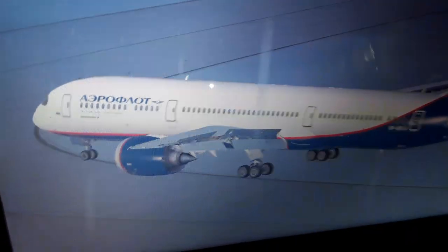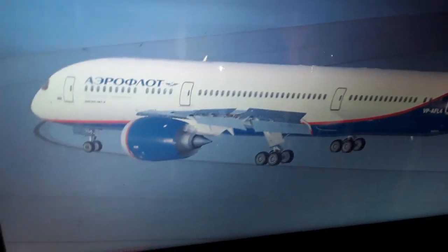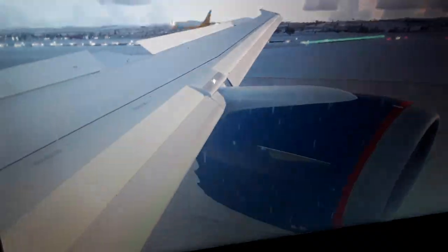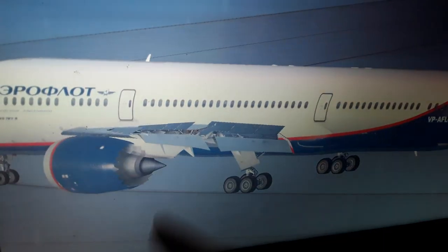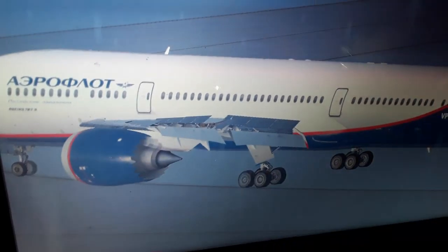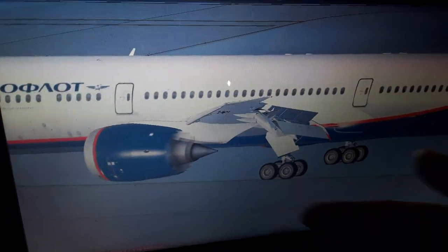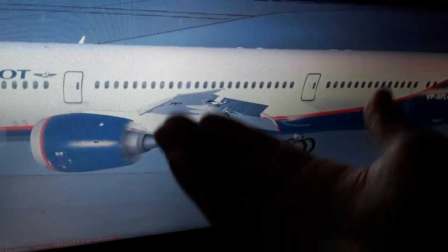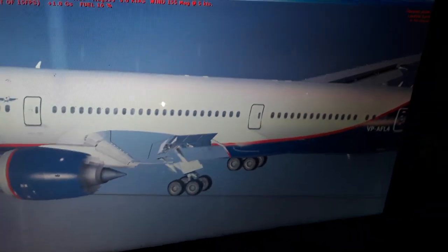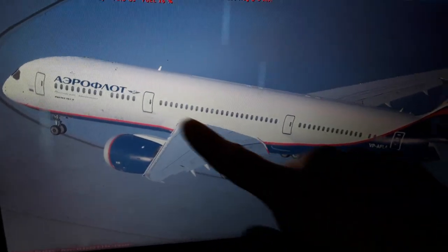And we have one more, the bottom surface of the wings. You can see we have the flaps extended, and as we accelerate for takeoff, the airflow moves slower below the wings, so we have higher air pressure, which, using Bernoulli's principle, pushes the wings and the weight of the aircraft up into the air as we accelerate to around 250 kilometers an hour.